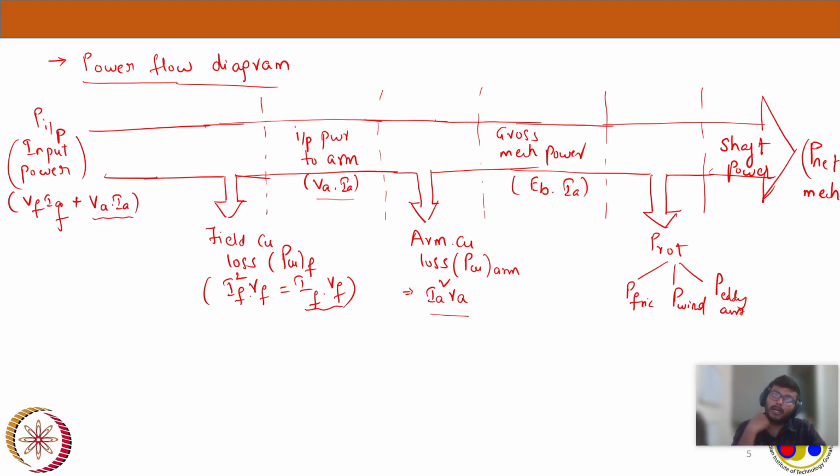So this is a very important power flow diagram when it comes to DC motor. There are many numericals to solve on losses in a DC machine. If you remember this diagram perfectly, it will be very easy to solve such numericals, because you know what all the losses will be, where they occur, what current causes which losses, and what are the constant losses, the no load losses.